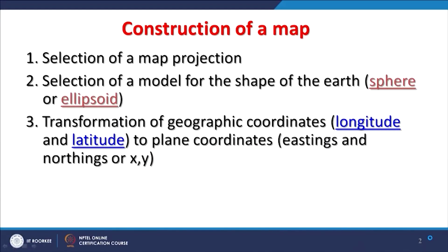Another issue is that GIS is very good at handling geographic coordinates in terms of DD or longitude latitude, and the plane which we use for a map is again a flat plane. So that means these curved lines have to be made straight lines on our maps, or a little curved, and therefore problems about accuracy of measurements will arise.